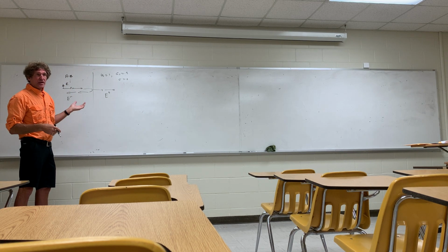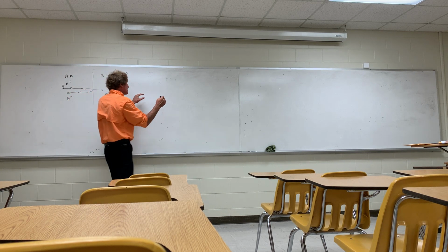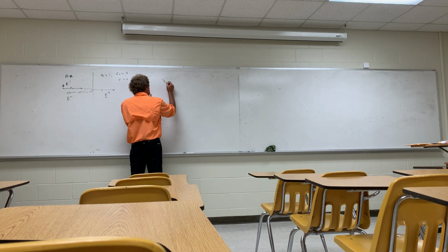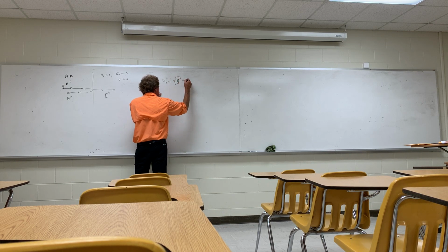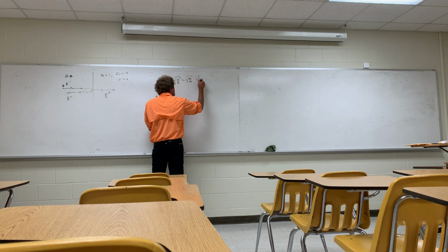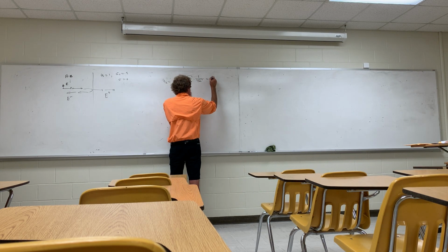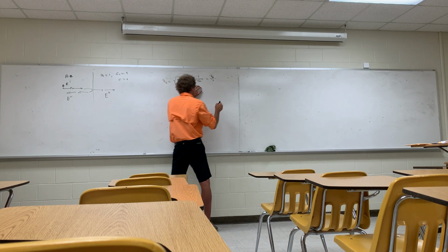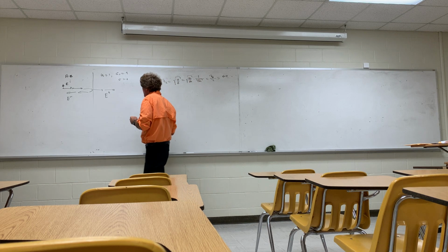We want to figure out power and what the E fields are in both regions as well as the power density. So we'll start by finding first the intrinsic impedance in region 2. And that's technically the square root of mu over epsilon, which is square root of mu naught over epsilon naught times 1 over the square root of epsilon relative, because everything else is just the free space values. So that's going to be equal to eta naught divided by 2, because epsilon relative is 4, or it's 120 pi divided by 2, or 60 pi. But you can leave it as just eta naught over 2.